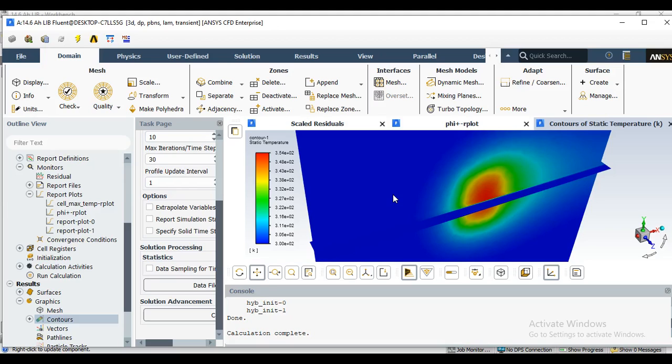If you want to get that simulation data, you need to simulate the battery cell without the channels with the same input data as the short circuit condition and the short circuit region, with the same external resistance value and with the same short circuit resistance. You can do that on your own. And then we compare the results and see how this cooling channel helped the battery keep from thermal runaway.